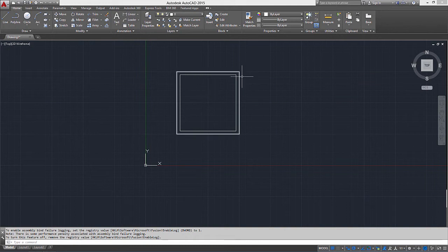Now we are going to round off the corners of this. We're going to do what they call a fillet. A chamfer is to chop off at an angle, but the fillet is to round these things off. So we'll use the fillet tool. Click on that, and then if we just click 2 lines, it's not going to do anything because our fillet value by default is 0.